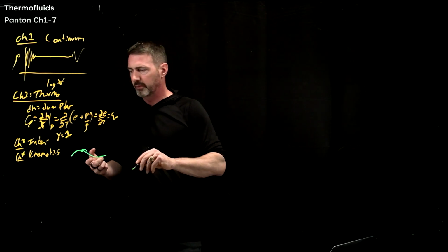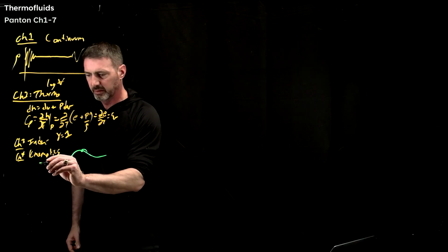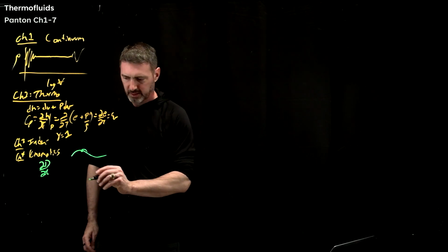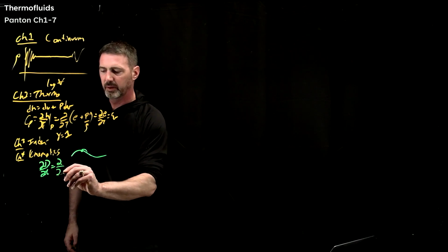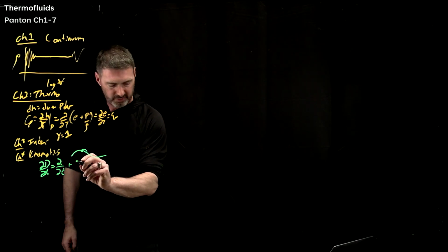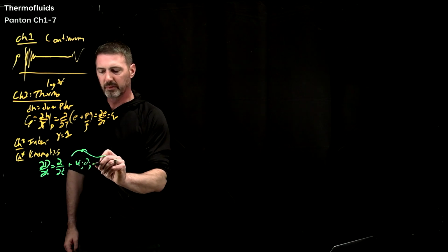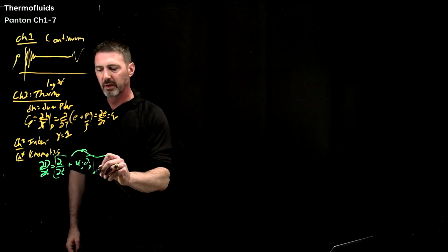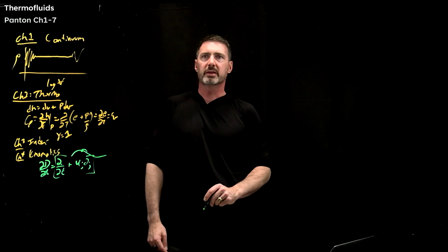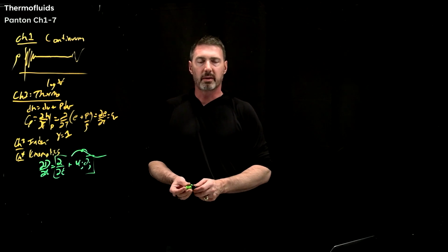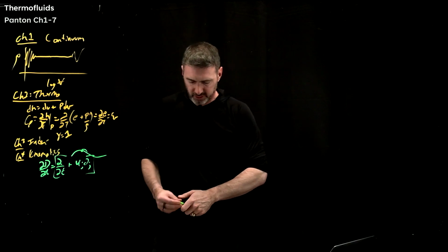And then for sure there's the definition of the material derivative. We're going to see this a lot, and really that's just the time rate of change, plus, I'll just say, u_j del_j of whatever you're doing. So that's the material derivative, and it's going to have that convective term in there. We'll simplify this a lot, and Panton goes through and rederives that. So it's good. Okay.